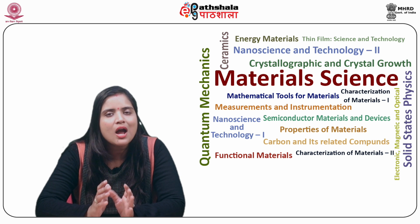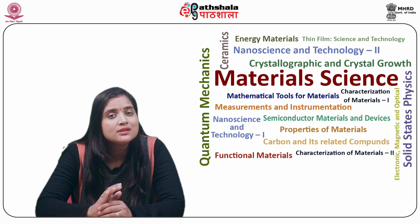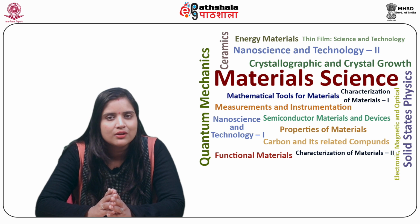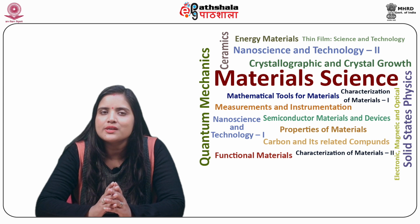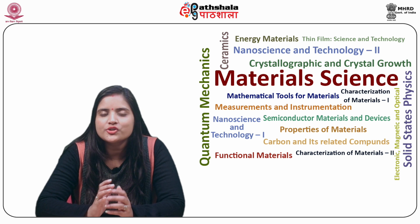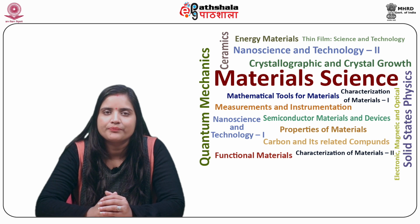Owing to high uniformity of the deposition, there is no need for post-treatments such as grinding. Electroless low phosphorus nickel plating provides superior corrosion resistance towards alkaline conditions.